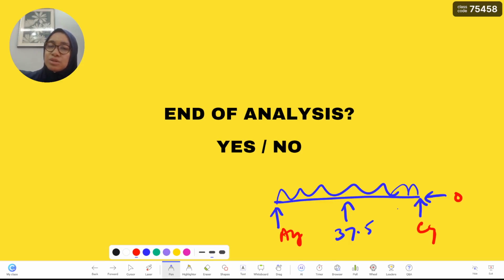Okay, so this is the flexibility method. Remember, we use the flexibility method whenever we have a one-degree indeterminate structure, whenever the 3 equilibrium equations are not enough to calculate the reactions, then we have to apply the flexibility method.